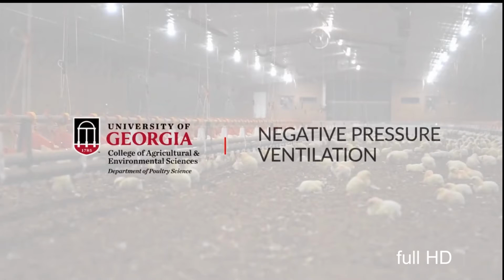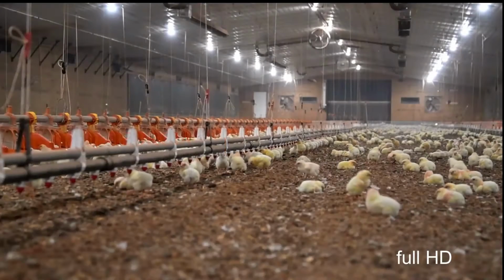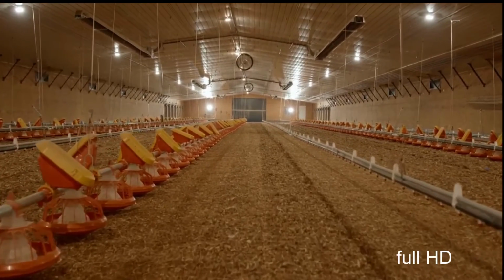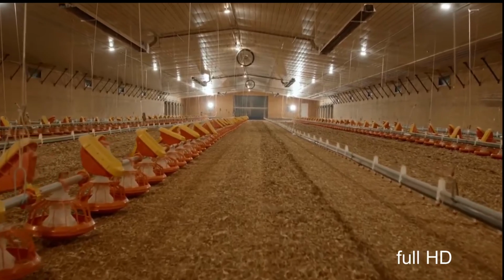One of the most important aspects of an environmental control system is we need some way to bring in fresh air. We need to bring in fresh air, not just to control air quality to keep our birds healthy, but also to control the house temperature, because the hotter it gets, the more heat the birds produce, the more fresh air we have to bring in to maintain a consistent temperature. When it comes to a negative pressure system, one of the most important aspects are our exhaust fans.